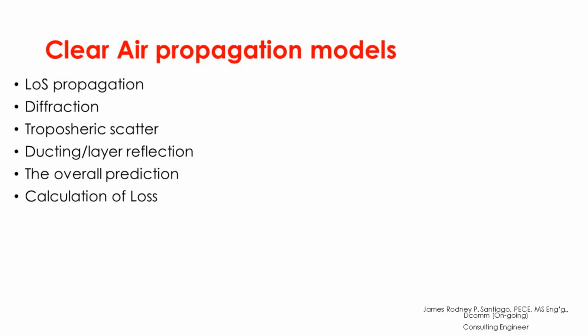And then the ITU-R P.452-18, where 18 is the latest version, which was released last August 2023. This is a prediction procedure for determining interference between stations on the surface, in the radio horizon, also for frequencies above 100 megahertz.